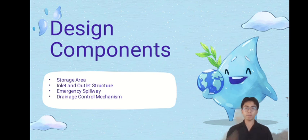The third one is the emergency spillway. This emergency spillway is a safety feature that prevents overtopping during extreme rainfall events by directing excess water away from critical areas. And the last component of the stormwater detention system is the drainage control mechanism. This may include orifices, weirs, or valves to regulate water outflow precisely.